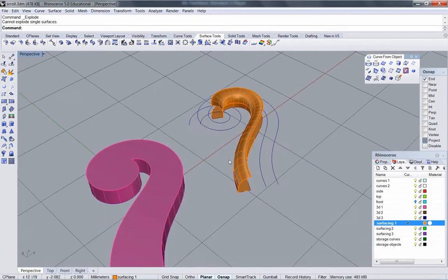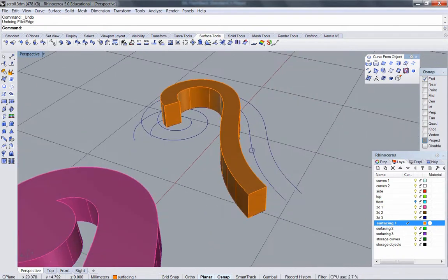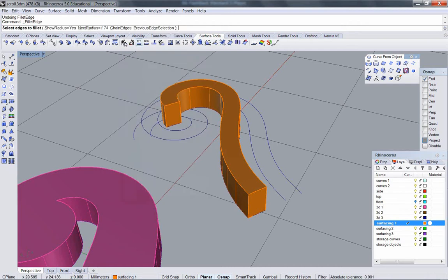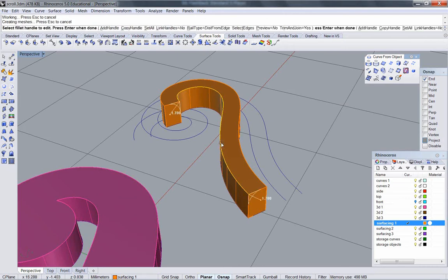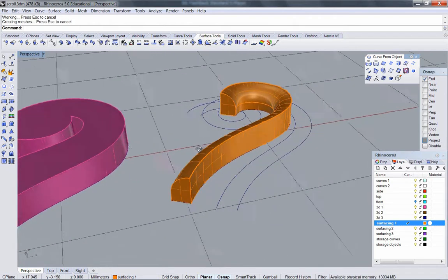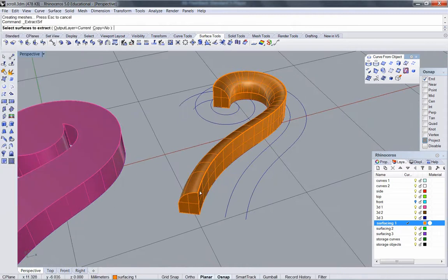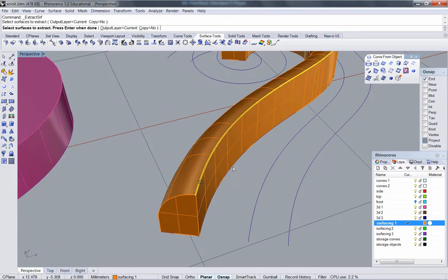Now if I wanted to avoid that, and it would be smart of me to avoid that situation, I could fillet it at just a little smaller than 1.74. I'll make it 1.7. Okay. That way, it's clear that there's this little extra surface here all the way along.